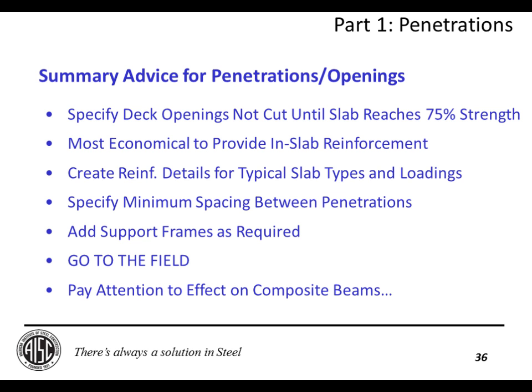And one piece of advice that I think holds true for most everything is to go out to the field. If I hadn't gone to the field on those 2 jobs, that conduit would have just been covered up in concrete and I never would have known the difference. Hopefully there wouldn't have been a problem, but there could have been. So you never know what you're going to see. I would recommend you get out there before that concrete's placed.